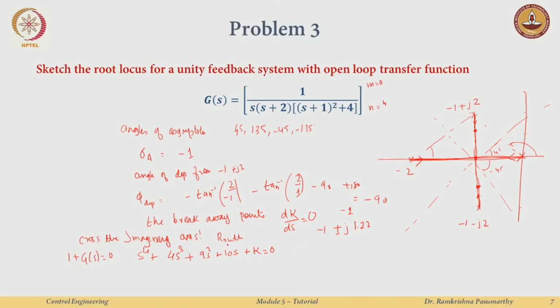And I do again the Routh table and what it gives me is that there is again k at a number 16.25. I will skip all the details, by now you should be experts in computing these, and also at an omega 0 of 1.58, right. So, they cross the imaginary axis at this point, okay, I am just drawing approximately, again not to scale, this is 1.58 with a minus sign, this is 1.58.